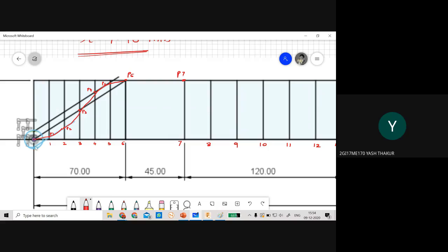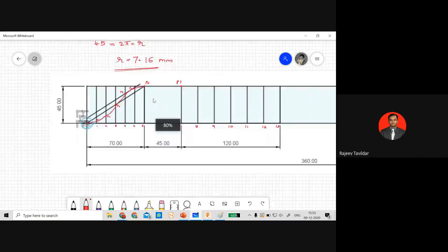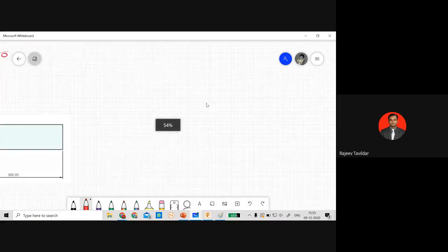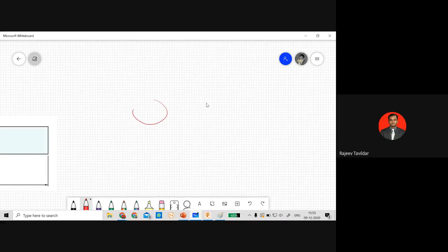Yes, sir. See, for this cycloidal circle, you do numbering anyhow, whatever it is, clockwise or anti-clockwise. Ultimately, what I want is, I'll draw a rough sketch here. For a given circle, I want one horizontal line at the top, and one horizontal line at the bottom. This is how the division has to be made.